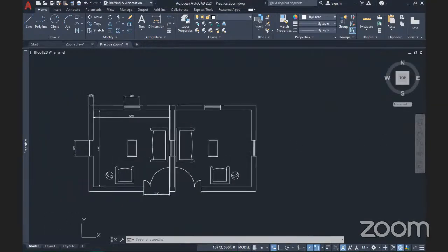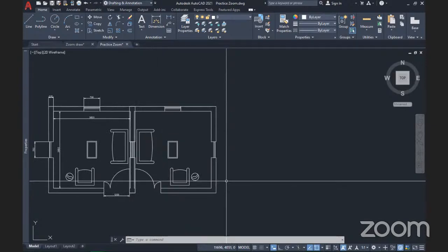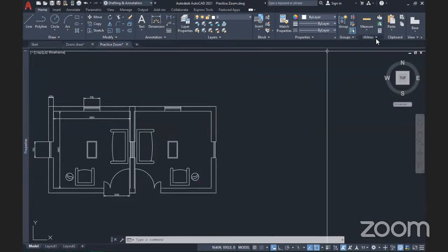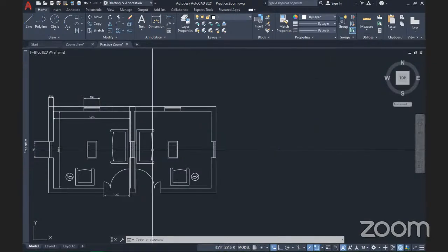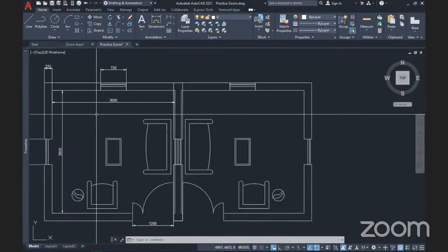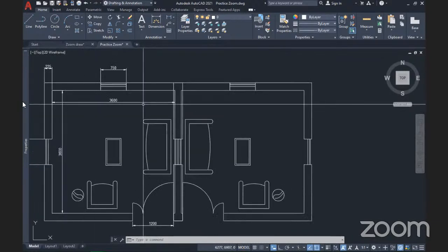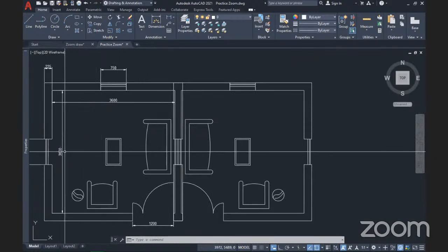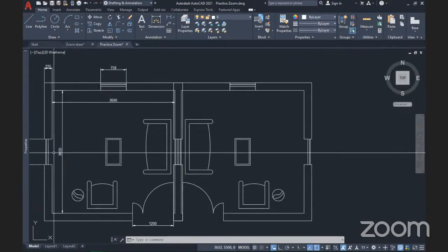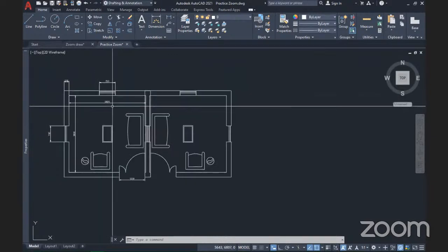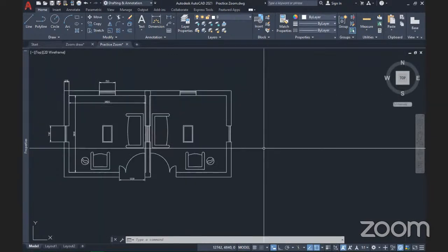Now, for us to create this building, we have to be technical here. You know, if you want to draw something, you need a known point to start from, where you're comfortable with, and then you progress to the point that seems like it's really unknown. But the truth is, if you start from the known, you will actually get clues on the unknown. So which is the known here? You can see the known is a box inside of this building, which is that square that is 36 by 36, 3,600 by 3,600. So I'm going to start there, and I'm going to use the